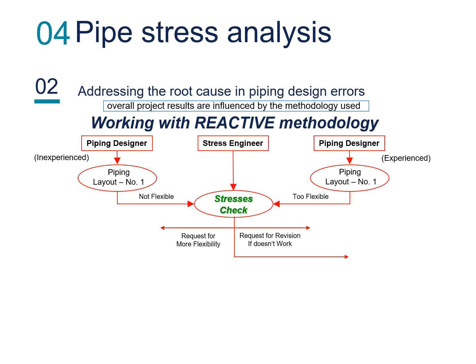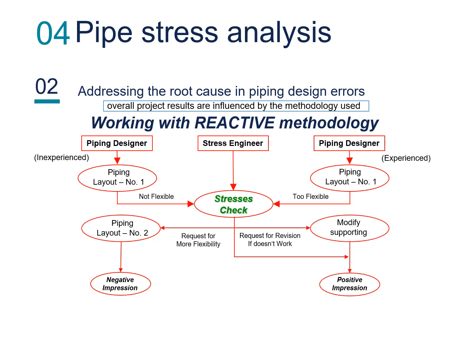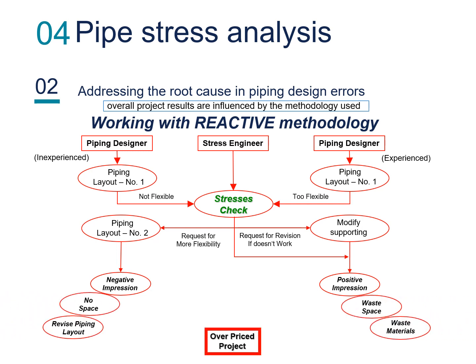In both cases, the stress engineer would be requesting layout rework, the difference being that the inexperienced designer would be given a request to produce a new layout concept with more flexibility, whereas the experienced designer would usually be required to come back with a modified supporting configuration, while keeping the same layout. In the end, either side will affect project results in a negative way, with the inexperienced designer affecting the project through a slow process and long schedule, while the experienced designer will affect the project through wasting space and the excessive use of materials.